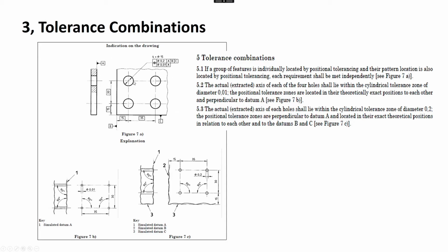So in this case, there's two tolerance zones. These holes need to be accurate to themselves within this bottom tolerance, and also to the front face as well. So these holes need to be very accurate to the front face you're drilling into. So they need to be in effect very, very square through this distance within this value here. But it's also controlling the pattern relative to itself in this direction and in this direction. So the 30mm dimension and the 35mm dimension sort of come into this box here, and also the squareness relative to the top face comes into this bottom box.